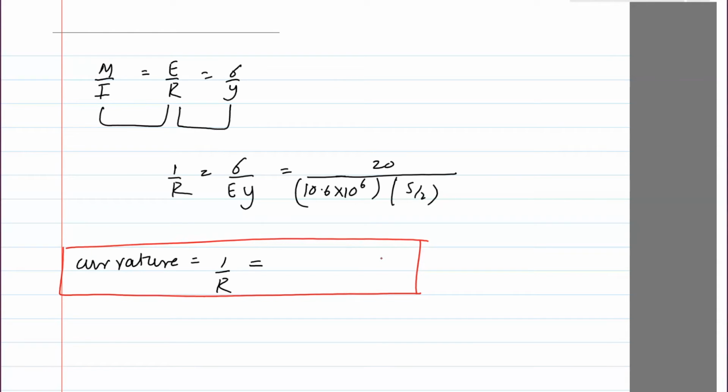Okay, so what's the unit? So on top we have sigma, it's in KSI, and then E is in PSI. So I think I need to convert that. It should be 10 raised to 3. And the answer should come out in inches.